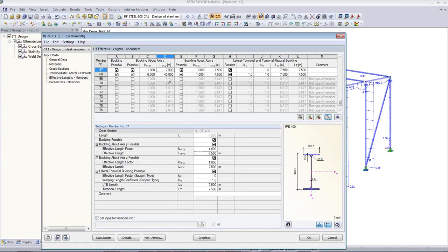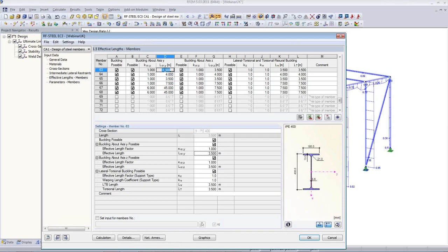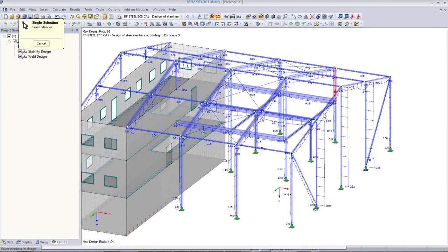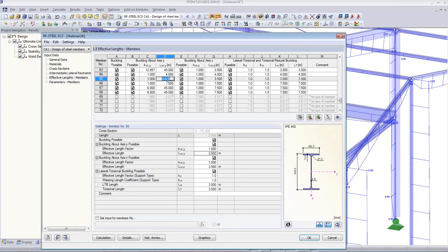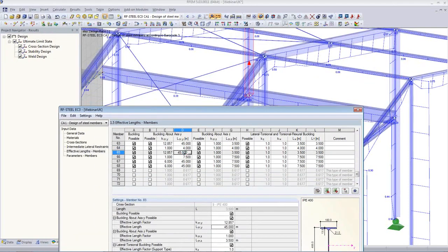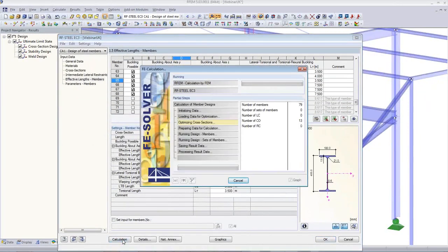We do the next column, and I can just copy, for example, this value with copy paste, and I have basically 4 more columns to do. This one, and copy paste here as well. So I can check it. Seems to be okay, and I run my analysis now one more time, and I have a pretty good idea whether it's even controlling this buckling in this case.